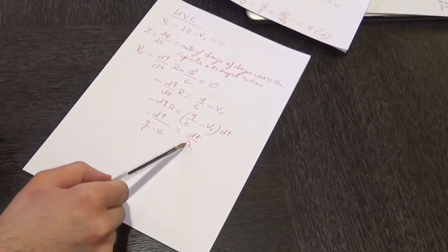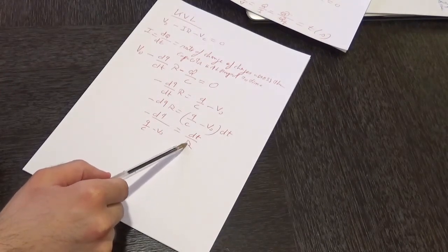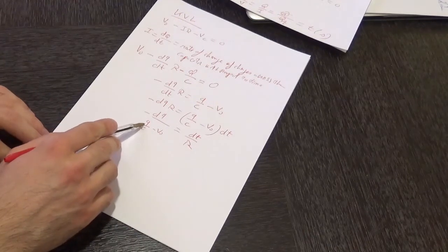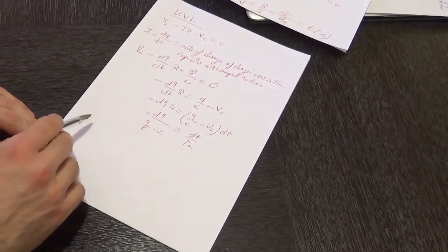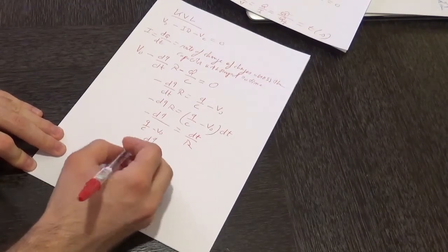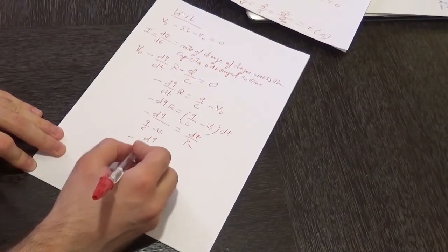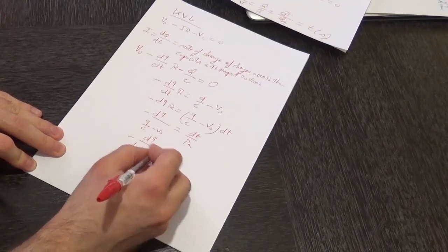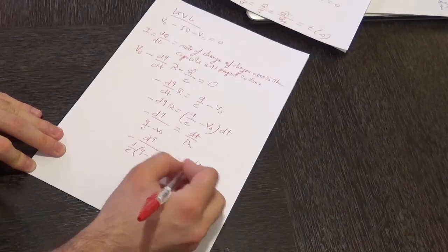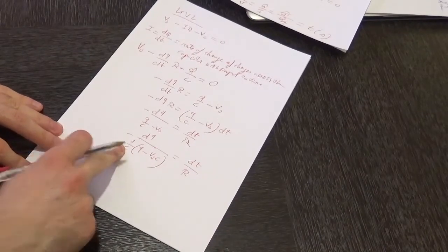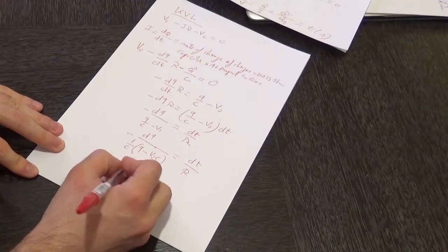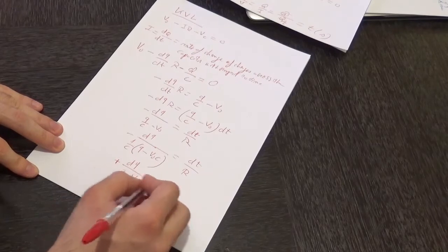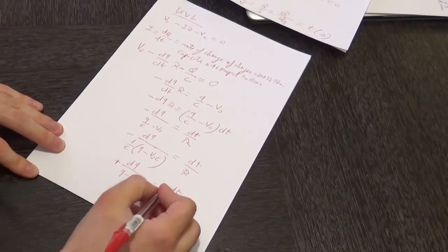So over here we have only the term r, and we need to multiply r by c in order to have a term for the time constant. So for that matter, we are going to take over here a common factor, 1 over c. So we have minus dq over 1 over c taken as a common term into q minus v0 times c, which is equal to dt over r. And then we can take c to the other side, and the equation becomes minus dq, or we can take the minus to the other side as well. So dq over q minus v0c equal to dt over rc, and the minus sign over here.